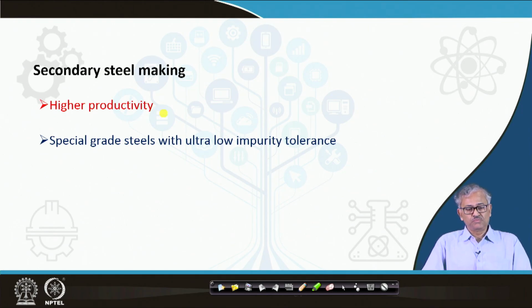That is the crude steel we produce under the primary steel making unit, because then the liquid is poured into the ladle, and the tapping ladle will move from the SMS to the caster. During this movement there is also a lot of time, and there we can do further processing of steel to the requirement of the customer.